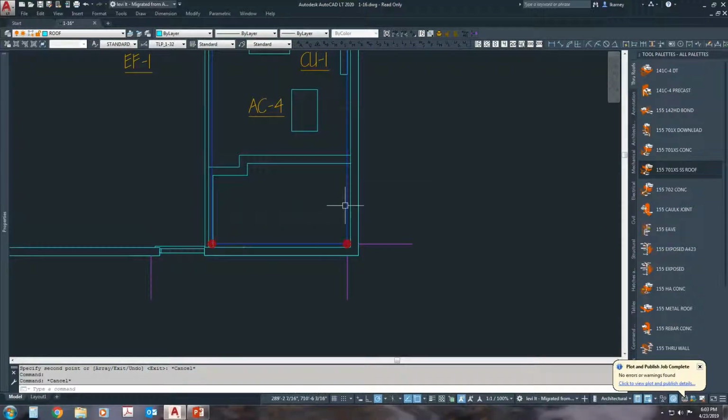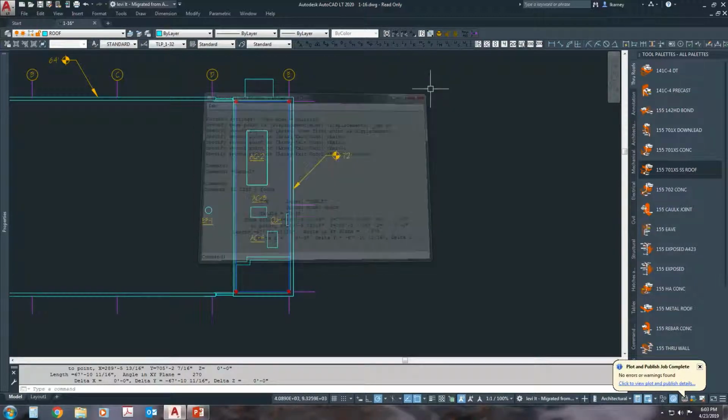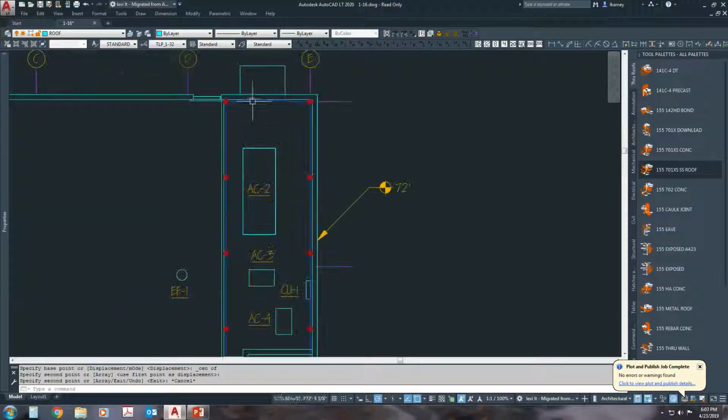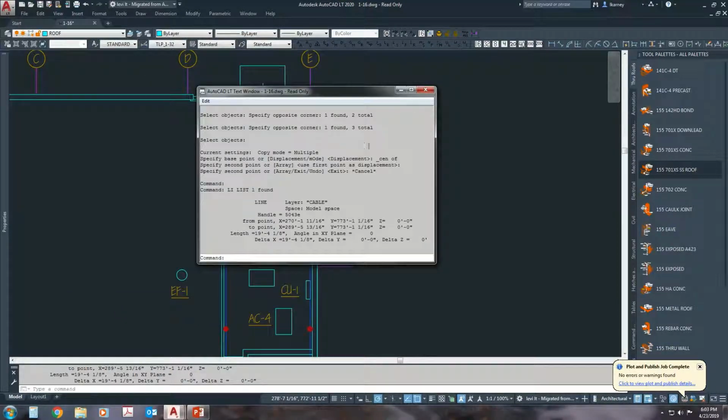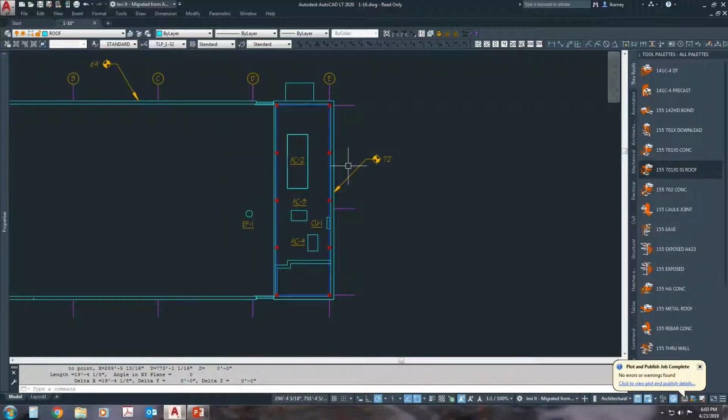Measuring the lines, you can see the distance here at 67 feet, which means every 20 feet on center, I'm going to have to divide this line by 4, giving me 3 evenly spaced air terminals. The AutoCAD that I have set up automatically has a divide command using that block. You can turn any symbol legend into a block and divide it by that using a macro.